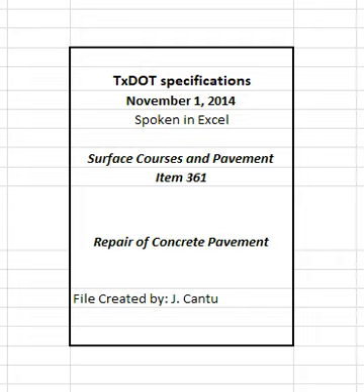Schedule work so that concrete placement follows full depth saw cutting by no more than 7 days unless otherwise shown on the plans or approved. Remove the slab by lifting the slab with a minimum disturbance to the base materials and surrounding concrete. Do not spall or fracture concrete adjacent to the repair area.